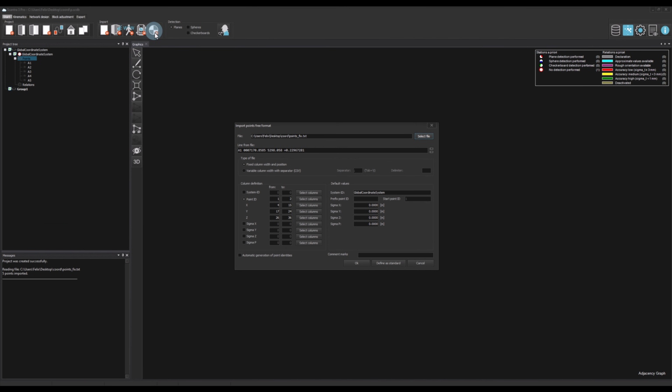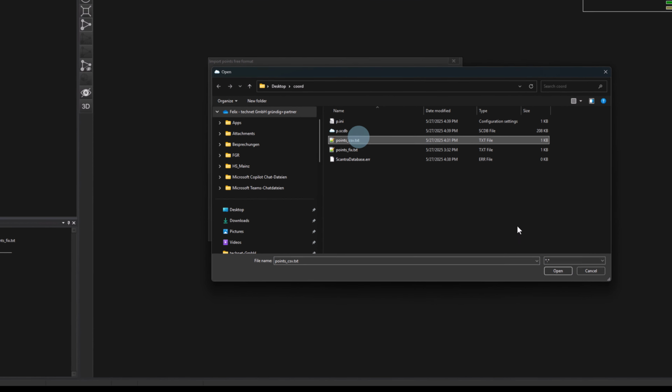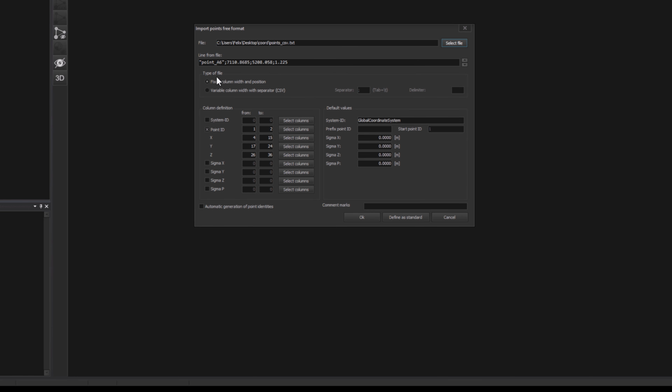For the second strategy for file decomposition, various separators can be defined for the CSV import. Should a line contain certain characters or punctuation marks that should not be imported, the delimiter text box can be used to define them. The association of X, Y, and Z values are mandatory.